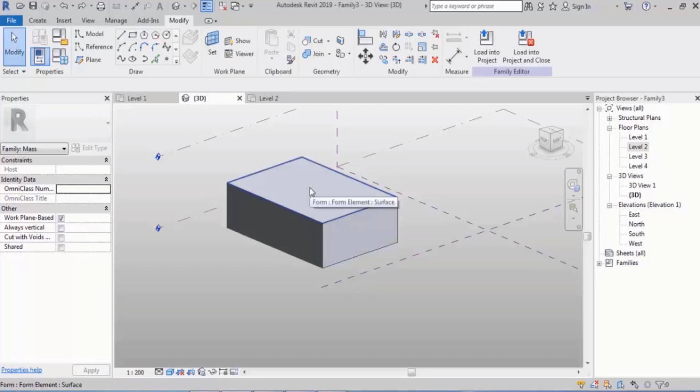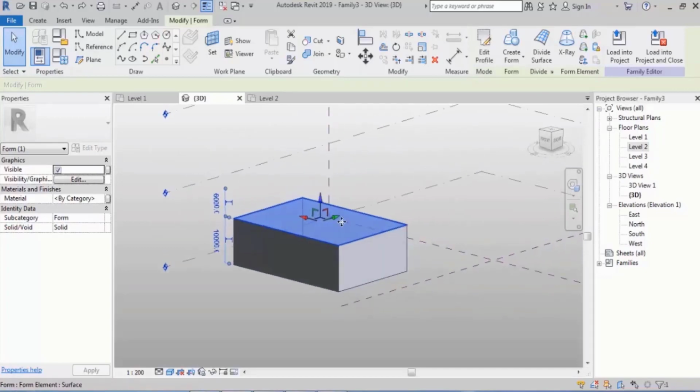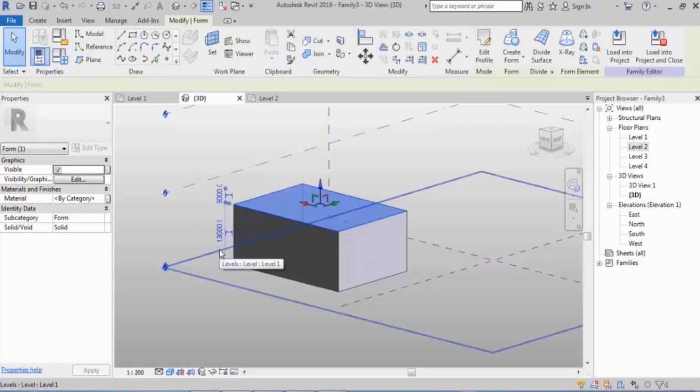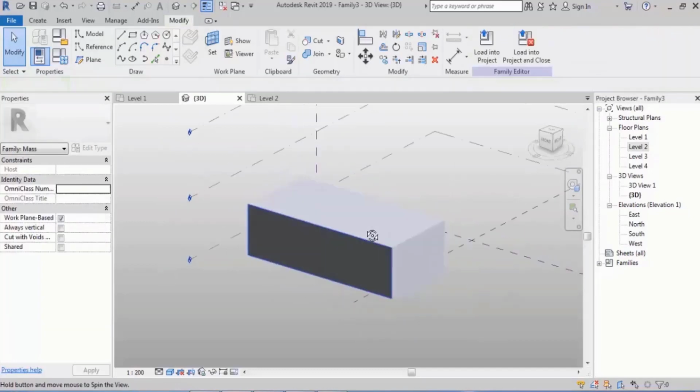So when you want to change the height of this, when you select it, you don't see any parameters such as height, width, or length. You don't see anything, right? So by moving each of these parts, you can change the height. For example, when you select this, here you can change this number to, for example, 13,000, right? By moving these sides, you can control the height or the dimensions in general.